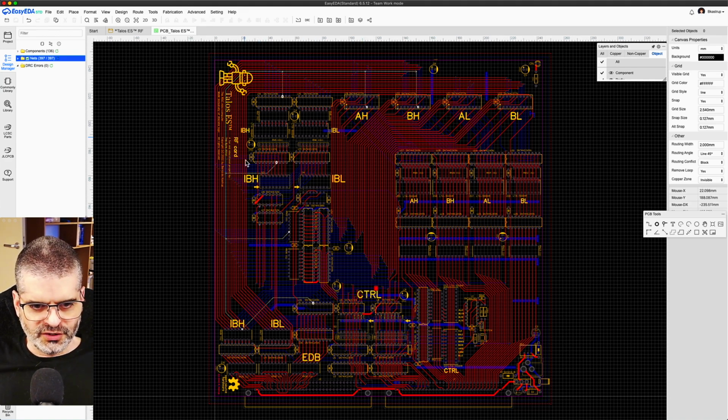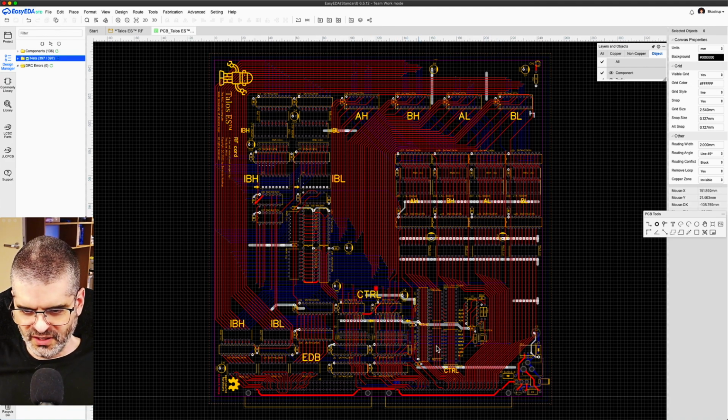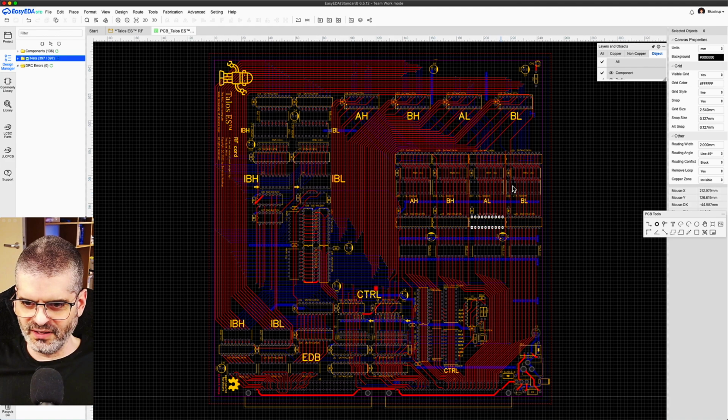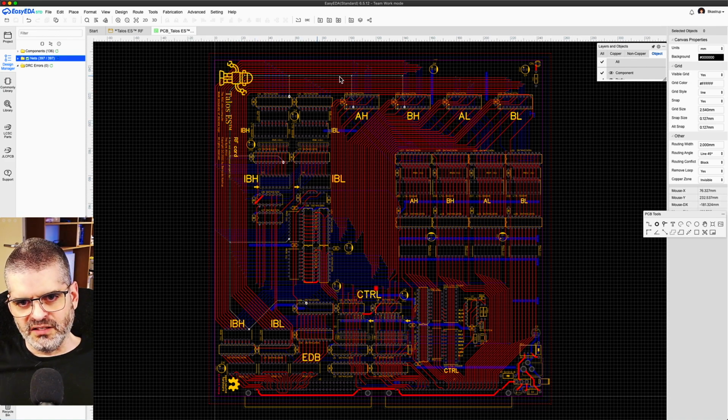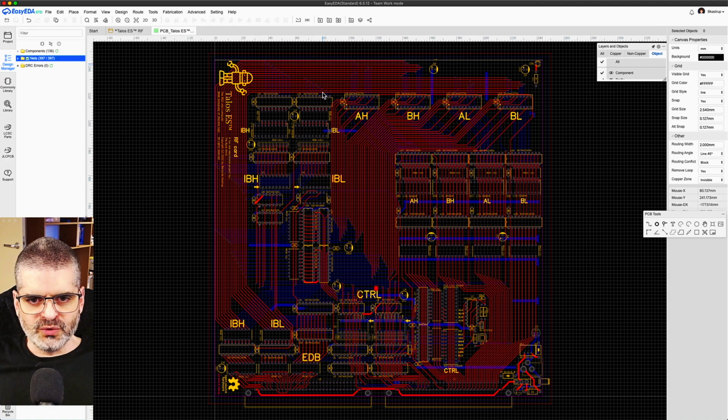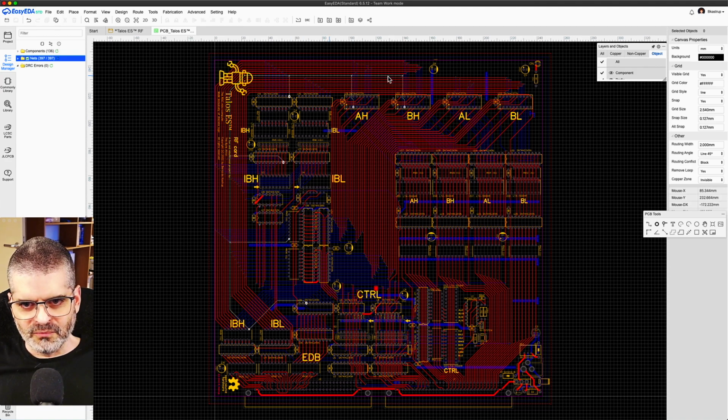You see vertical here, vertical here, vertical here, diagonal almost vertical here, all over the place, vertical here all over the place, there and there. But because I bowed the local bus here with a 90-degree turn, I didn't switch these lines of the local bus to blue. Because one, I didn't need it. I could just maintain them red and avoid one more via, one more layer change.